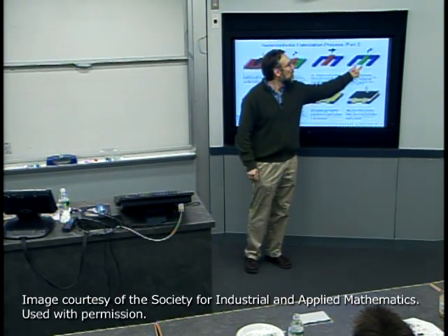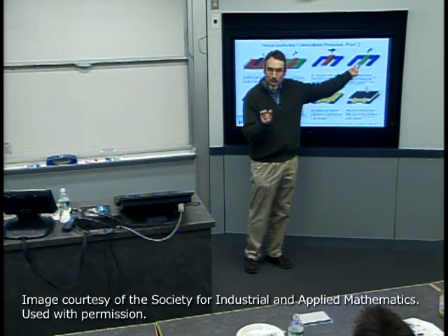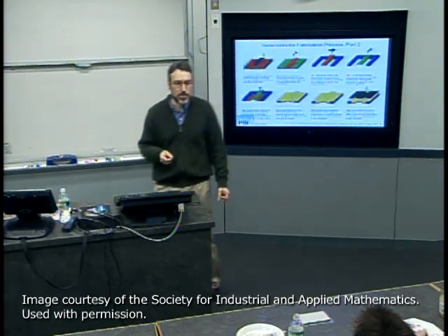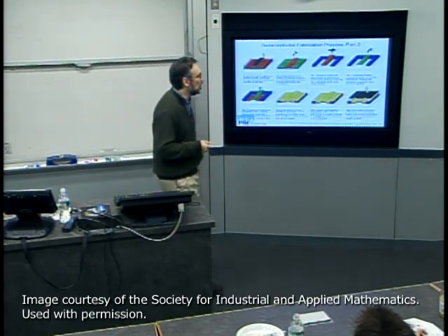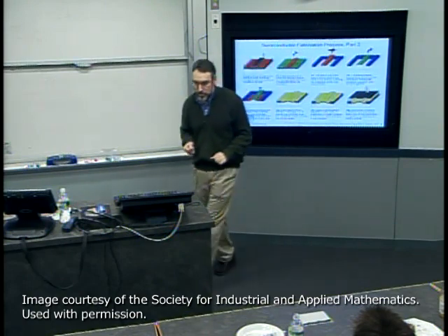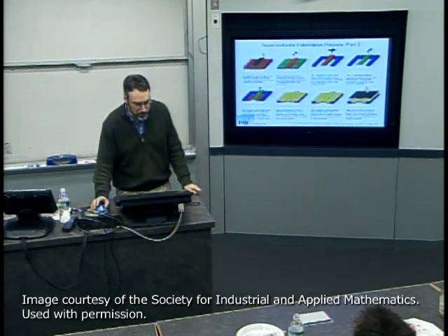In fact, often tricks are played where photolithographically, using the exposure, that's the dimension that they can form. But you might actually over etch and shrink that, get that to even a smaller dimension than you could photolithographically define in order to boost the speed and the controllability of the device. So this is a very critical lithography step and sequence.